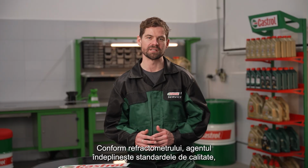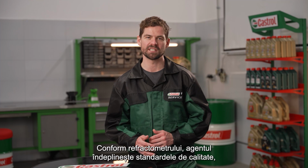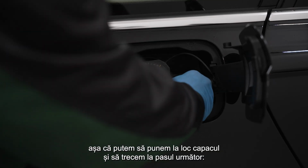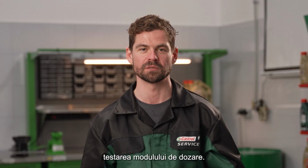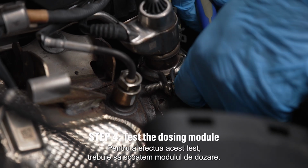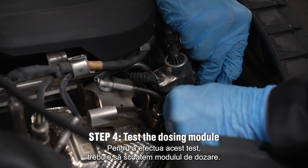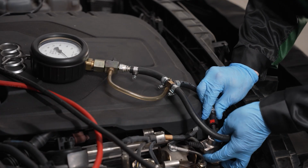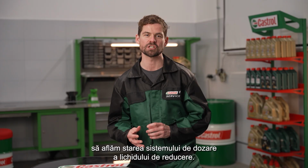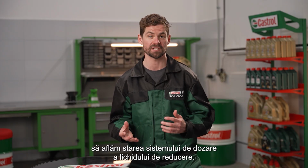According to the refractometer, the reducing agent meets quality standards, so we can put the blue cap back on and move on to the next step: testing the dosing module. In order to perform this test, we need to remove the dosing module. We'll also check the pressure generated by the delivery pump. That will allow us to determine the condition of the entire reducing fluid dosing system.